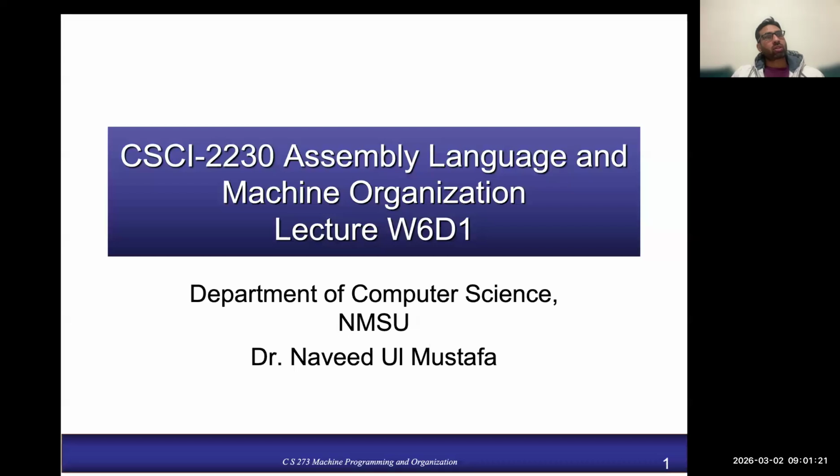All of those ports are 8-bit, other than port C, which is 7-bit. And again, it is 7-bit in the sense that 7 pins are available, but the internal registers which are responsible for configuring port C are also 8-bit, but the physical pins available are 7 in number, right?